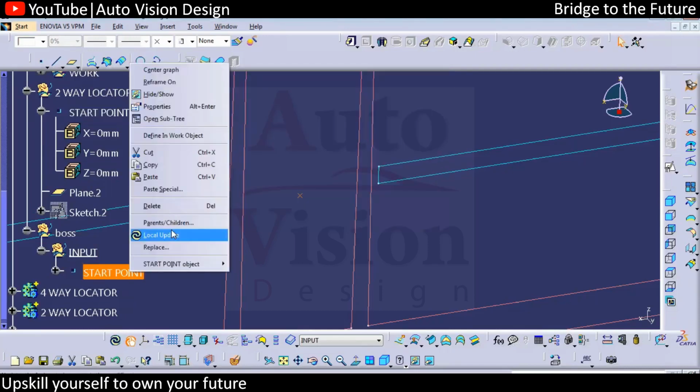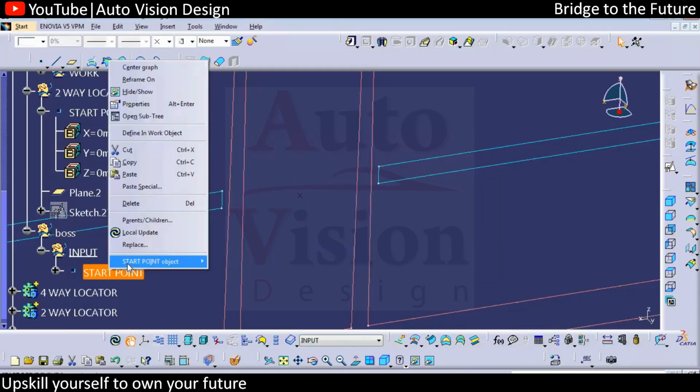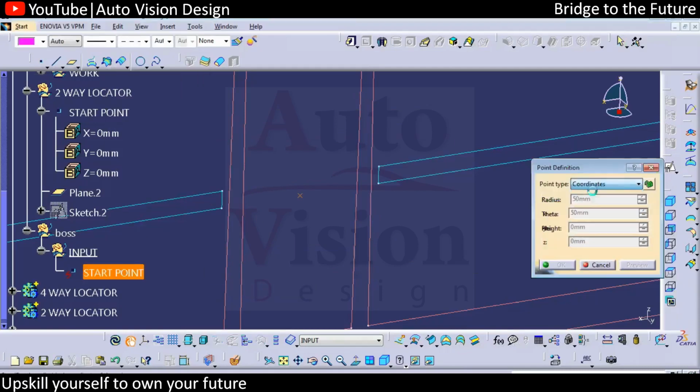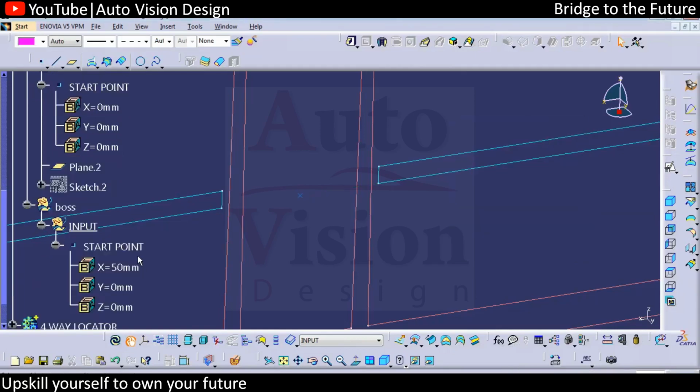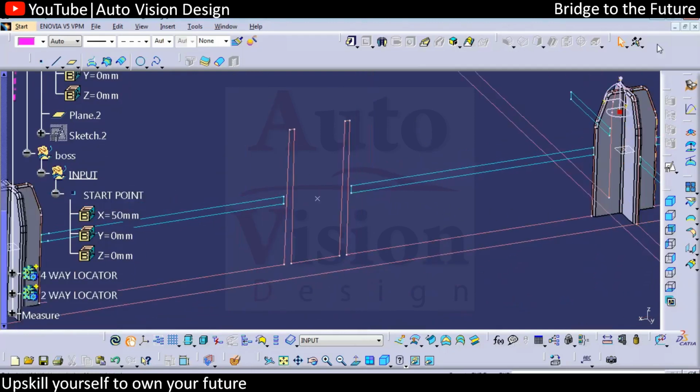So again, if we check the parameter, this is the link. We don't want a link, so you can click OK. Right click, isolate, double click, go for coordinate. So this is the trick to make it parametric within a fraction of a second. By that time, you can check this coordinate and select the point. It will take time, so we can directly create the point. And now we need to have the sketch. Add the sketch over here.